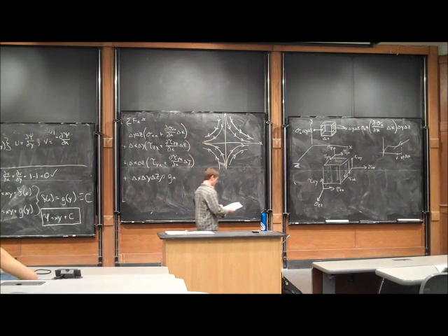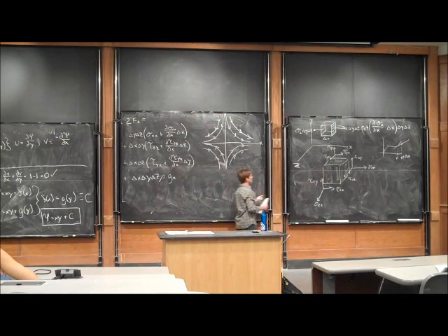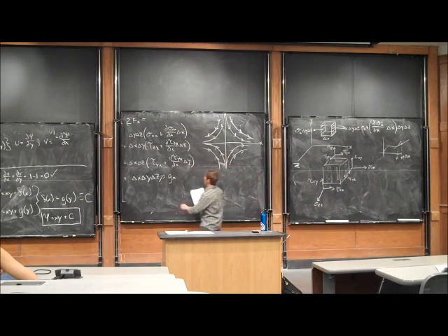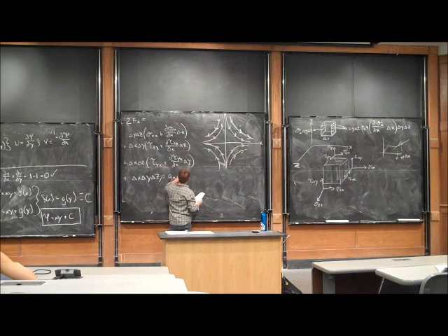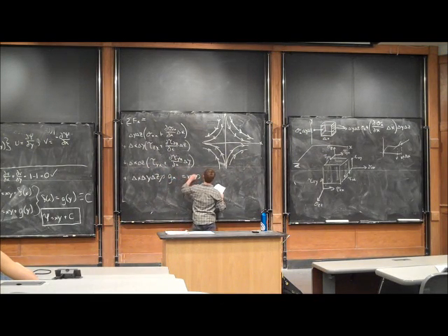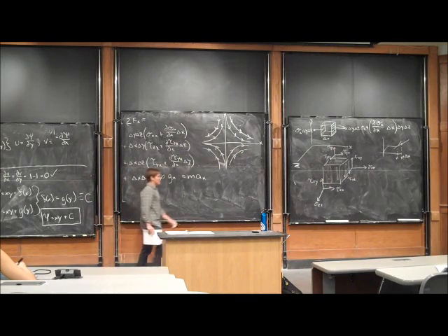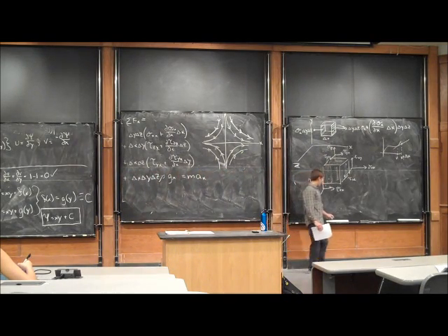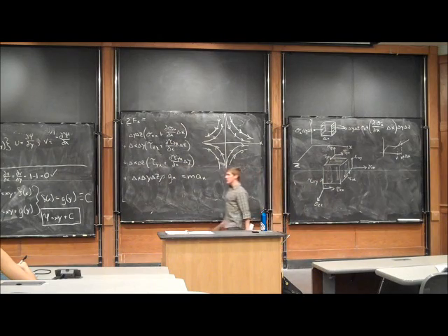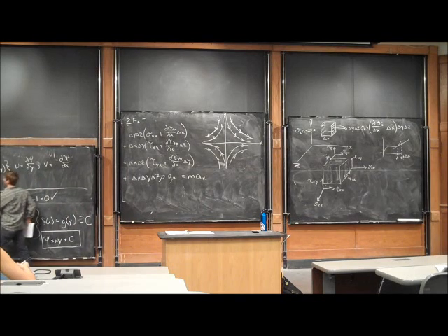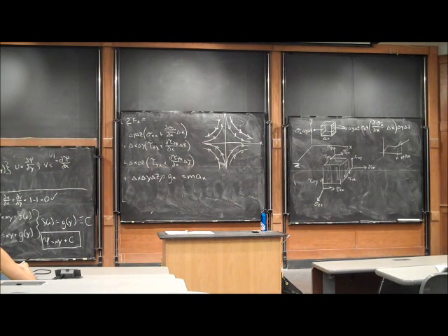Now we need to say that the forces acting on this element are what cause any acceleration we might see in the x direction. The sum of the forces in the x direction is equal to the mass of the element times the acceleration in the x direction. But in fluids, acceleration is not as easy as in physics 1 or kinematics. We're using the Eulerian viewpoint, and we have to use the version of acceleration that we derived earlier in the semester.